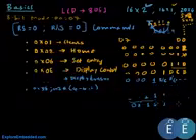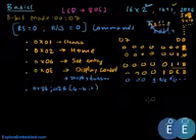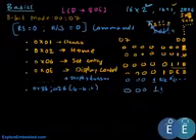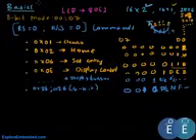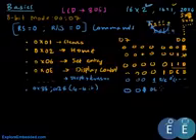So there is no default for this, since I would be using 2 different commands with the 2 modes. So this would be 001. This is called display length. This bit is called number of lines. This is font size, and this is don't care. Okay, now sorry, this starts here, not here. Let me just correct that. So this is display length, this is font size, number of lines, and don't care.